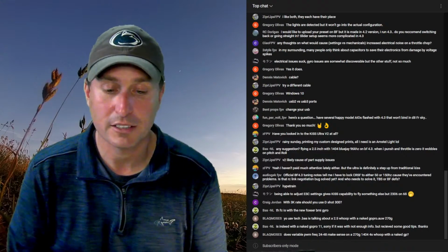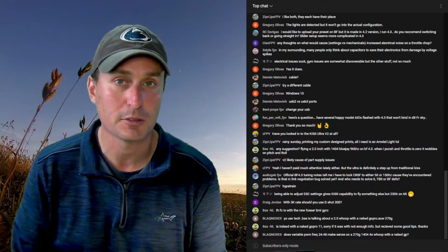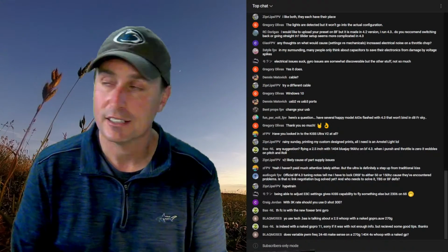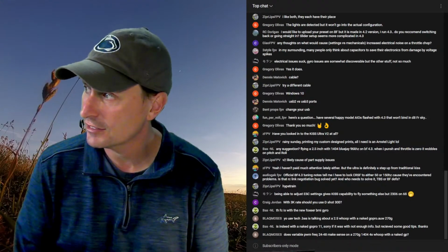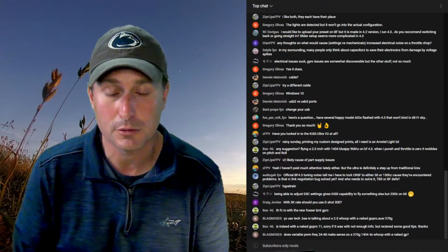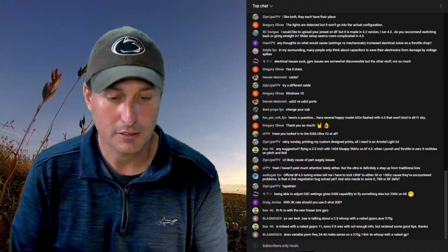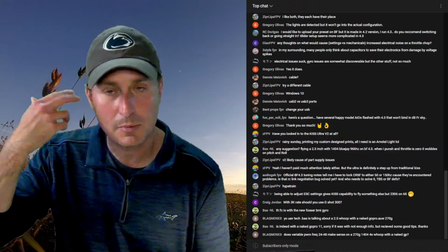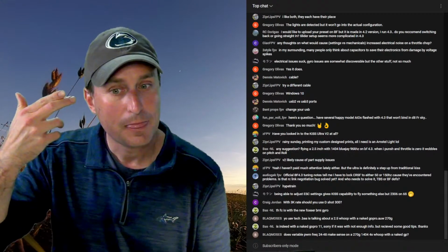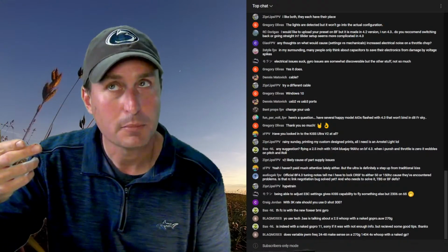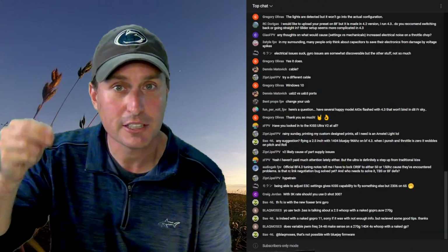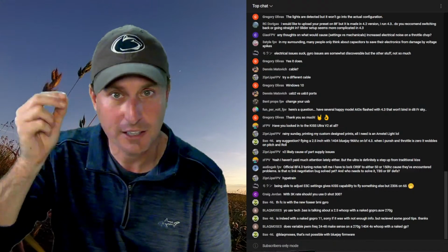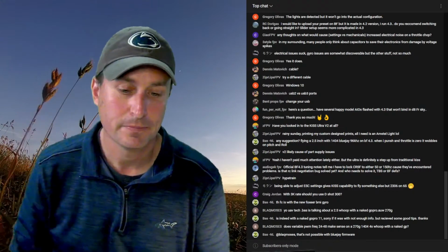There's no bug or anything like that. It just takes the flight controller a second to retrain. I think it takes half a second, a couple seconds, to retrain on the new frame rate. And obviously that can throw you off if you're racing. You've got to keep in mind that almost all the tuning notes are written by devs that are really, really into racing. So that's where they're thinking all the time. Racing, racing, racing, racing.